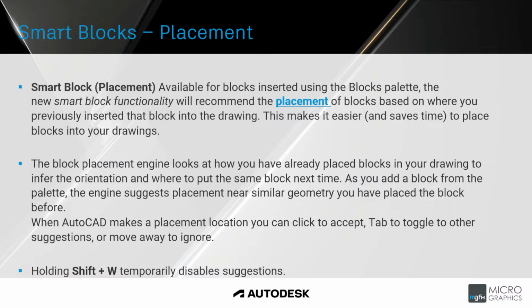Smart blocks. Smart blocks placement. Available for blocks inserted using the blocks palette. The new Smart Block functionality will recommend the placement of blocks based on where you previously inserted that block into the drawing. This makes it easier and saves time to place blocks into your drawings.